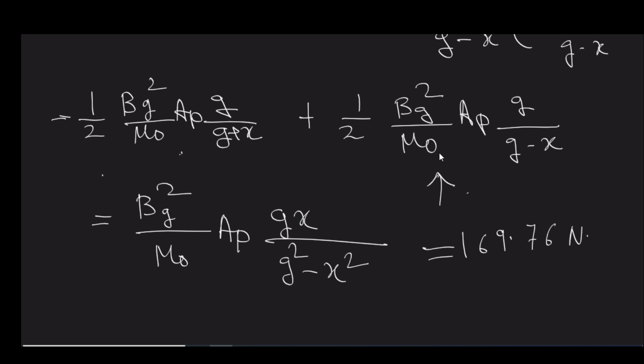So what happened in some cases when we fail to ensure proper air gap or symmetrical air gap between the pole shoes and armature, then the machine efficiency is getting affected by a huge amount. So that is what we should keep in our mind, that when we design a machine, we should make sure that air gap must be uniform.